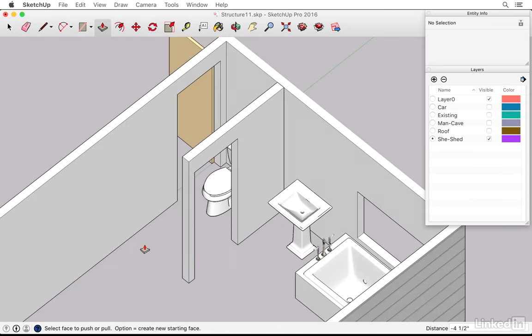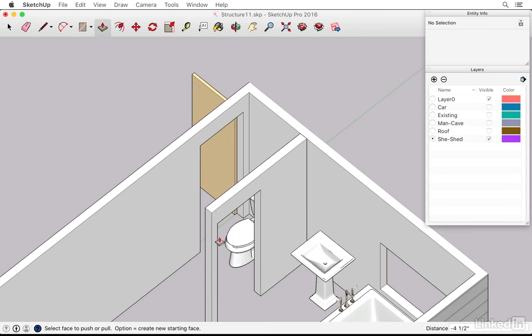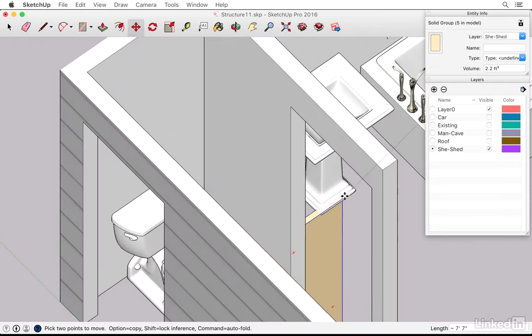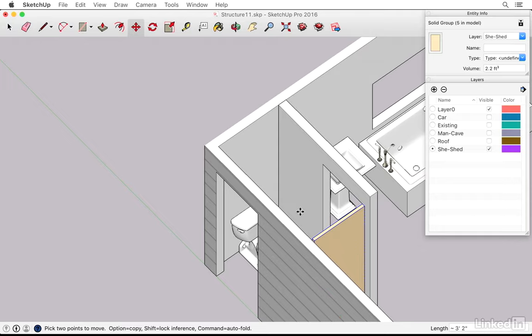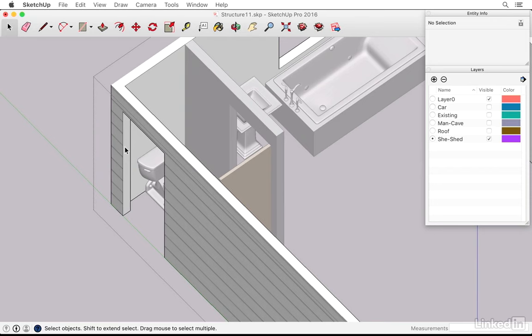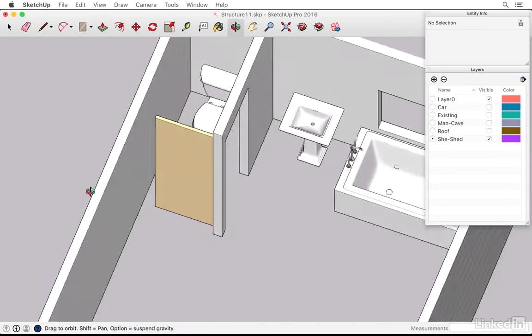The next thing I need to do is move this door over here into the new opening. I don't want to have an exterior door here on this washroom. So I'll just take the door that we already have and move it from this upper corner and place it right here. And while I'm at it, I'm going to double click on the exterior walls and then press P, and let's pull this over and snap it right here to eliminate the exterior opening.